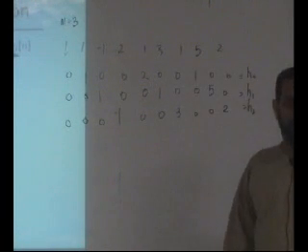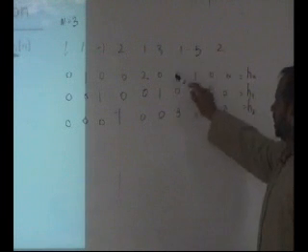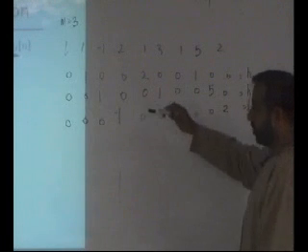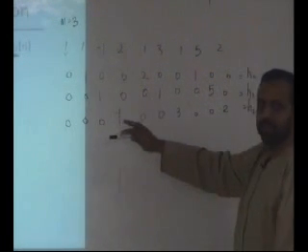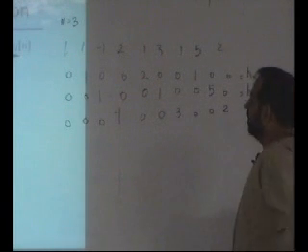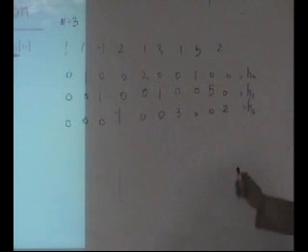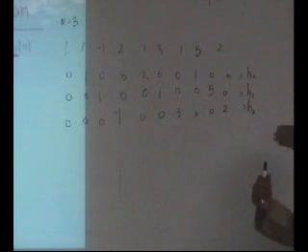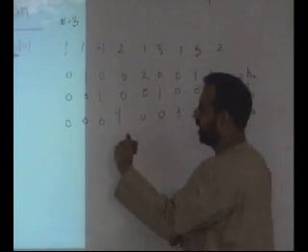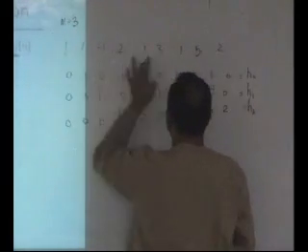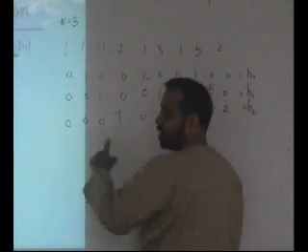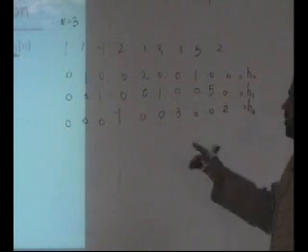I get this. So I know that this is equal to these 3 in parallel, and we have learned this in chapter 2: if systems are in parallel, their effective impulse response is the sum of all the impulse responses. But now there is some problem. What is the problem? If I take a signal, convolve it with this one, and this one. Parallel system means either you convolve it with this one, or you convolve it with all these impulse responses and then add. What is the problem in these?